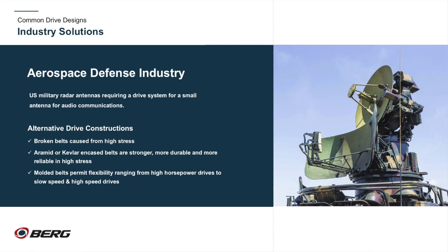We selected our FlexiPitch belt to replace the chain and use their existing sprockets. This enabled the system to run without lubrication and, because of the polymeric nature of the belt, without concern for the contaminants in the environment. Because we were able to use their existing sprockets, it was very easy for the end user to replace the chain in the field and have a functional system.